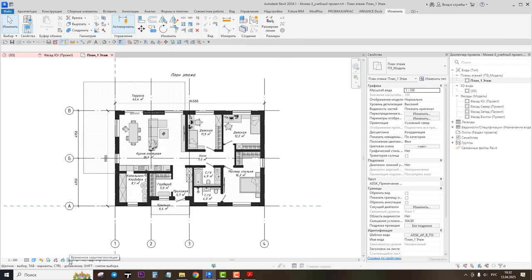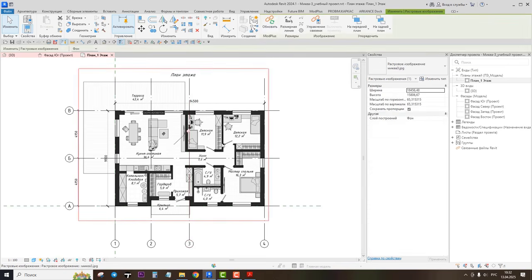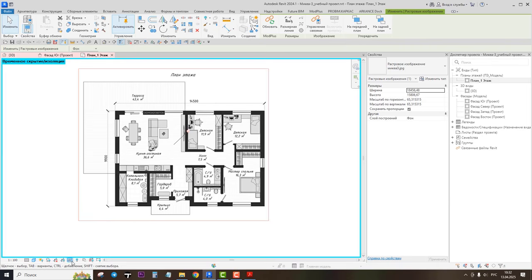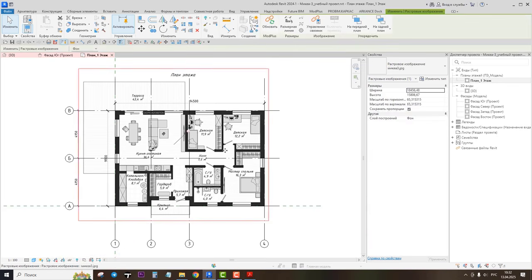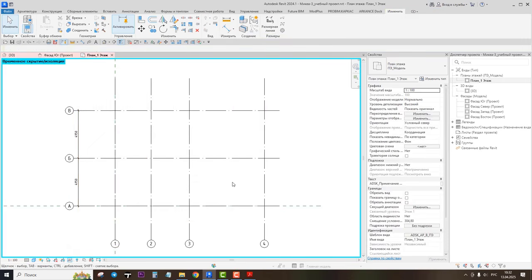Let me show you. You can, for example, choose an element, for example, this picture. Click this icon, glasses. You can hide the element. You can isolate it. If you isolate it, you make only this element visible in this view. Let's reset the temporary hide isolate. You can hide the element, but when you hide the element with glasses, you activate the temporary hiding. You see this blue frame around your work window.